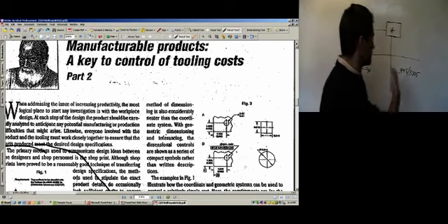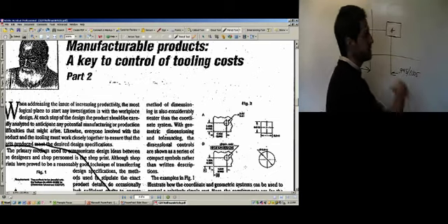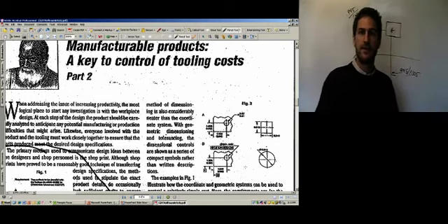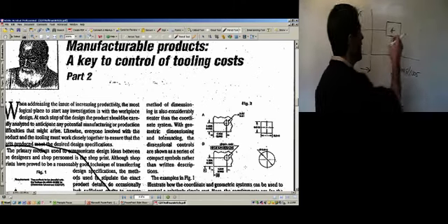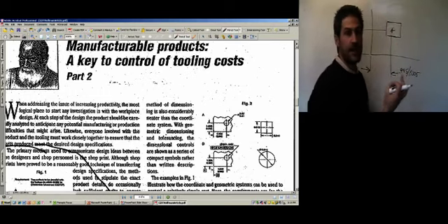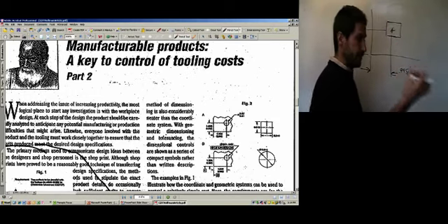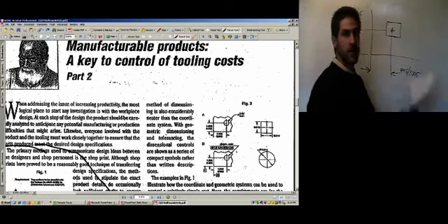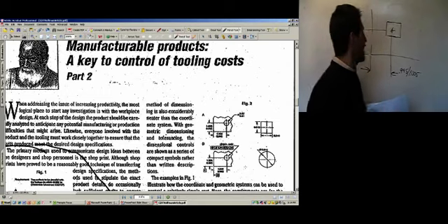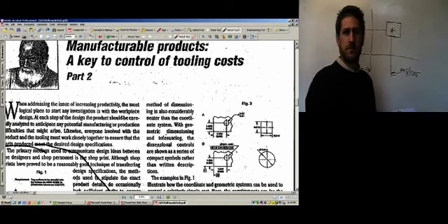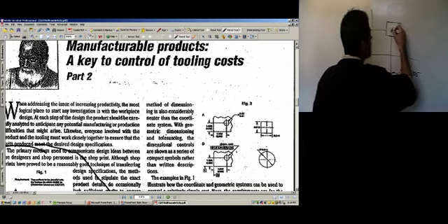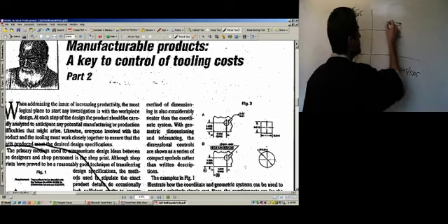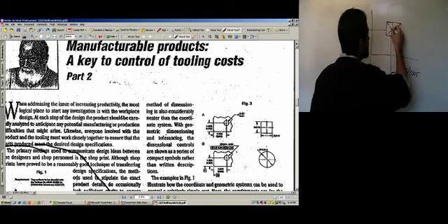I can be off a little bit this way, a little bit that way, and a circle is maybe a little more obvious in terms of putting equal weight to being off in each direction. If I'm going to have a pin and a mating part that's got to fit in our circle, that mating part could be off in either direction, and my hole can be off in either direction. A square doesn't really represent it well, because a square is saying that this hole can be off more in the diagonals than it can be straight up or straight to the side.